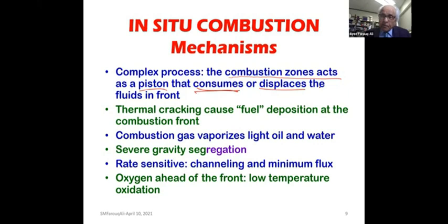So you see that has a huge implication. If there is a lot of fuel, then that combustion zone must burn it. You must supply enough air or oxygen so that it burns it. If there is water, then it must displace it. So this is an important aspect of the mechanism.